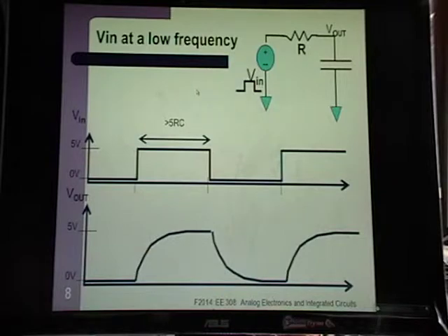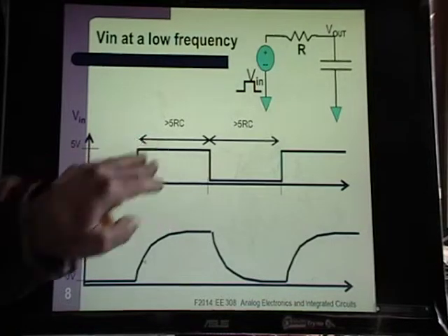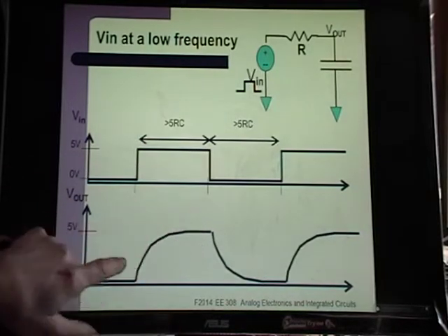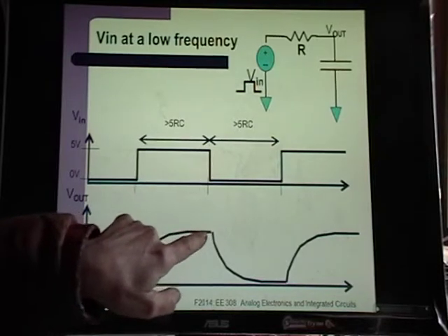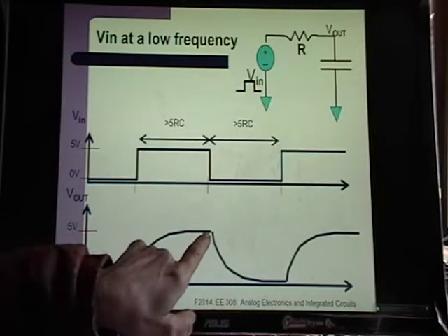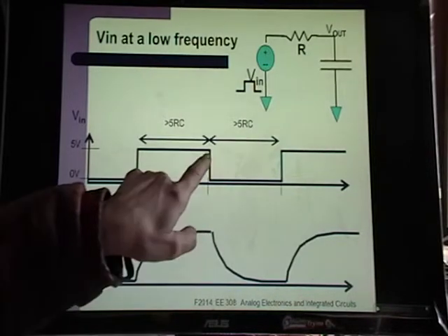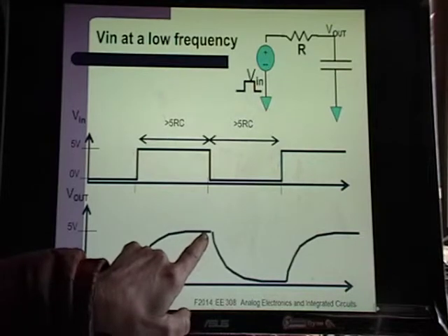There's a rule of thumb that I encountered in some textbook and talking to some people from industry, and they said, yeah, if you have a period of about 10 RC, then you consider the voltage of your output signal. So this is your input signal. Here's your output signal. If you are doing greater than 5 RC right here, you can consider this voltage basically as reaching its complete max voltage. In other words, this voltage and this voltage are the same in a filter.